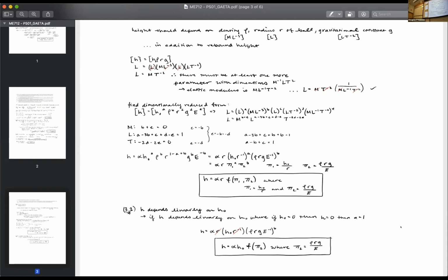So this is a good point that I'm glad got brought up. One of the assumptions that's baked into what you're presenting here, Leah, and you may or may not know this, is that the ground that it's hitting is effectively infinitely rigid. And that's a very reasonable assumption. You're dropping a bouncy ball on the ground, and the bouncy ball is significantly softer than the steel subsurface or something. But it's important to know that that assumption is baked in here.